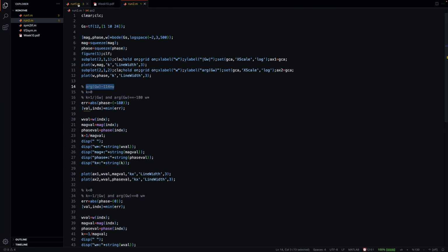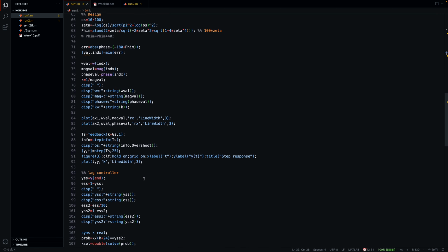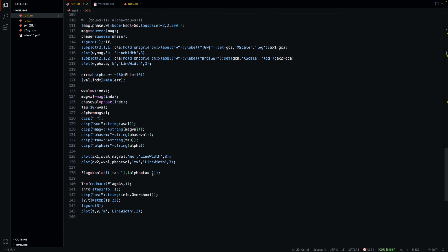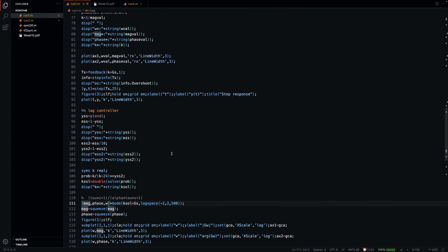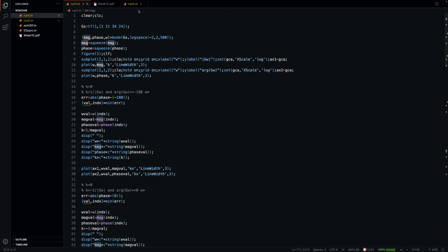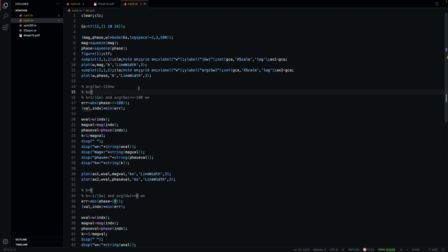Or as it was the case somewhere here, where we included the gain to the Bode plot, so we redraw the Bode plot of the updated system. That might not be possible. Then you have to basically look for K times G(s) in the magnitude plot. So if you update a column or add another column to your table, you will be able to just use the updated Bode plot. So sometimes the classical exams will force you to do such adaptations, because you will have a basic raw Bode plot table of, like, I don't know, 40 or 50 different values that are necessary for you, and then that's going to be it.